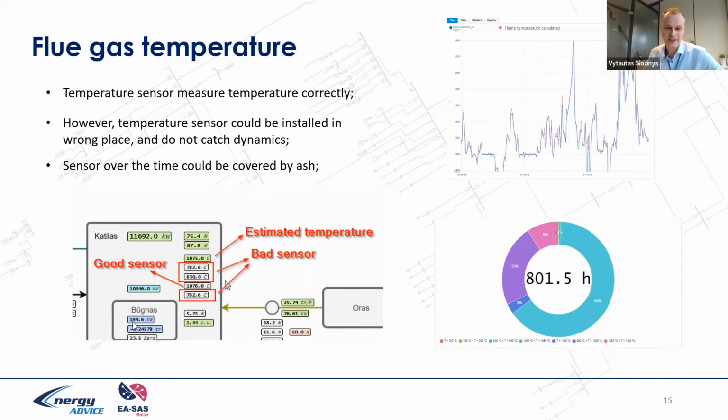So you can see here the trend of how the temperature metering and the flue gas temperature calculation behave in dynamics, and it behaves quite well. We also collect a historical chart trend of the distribution of flue gas temperature inside the fire tube for predictive maintenance. Why is it important?